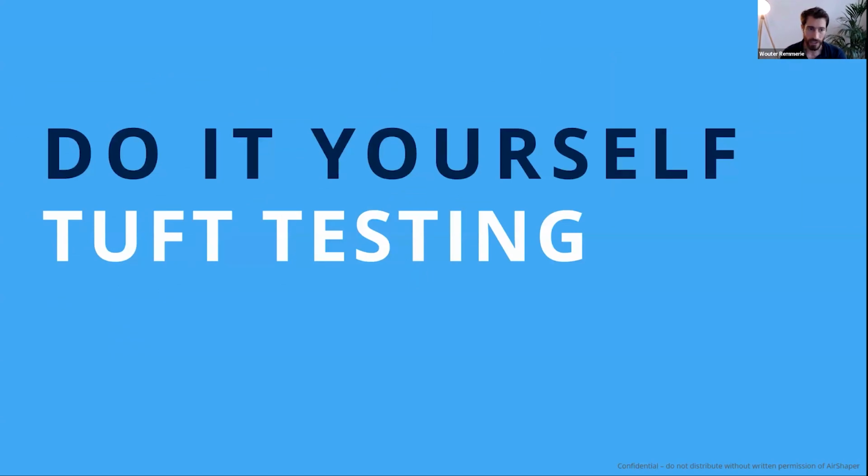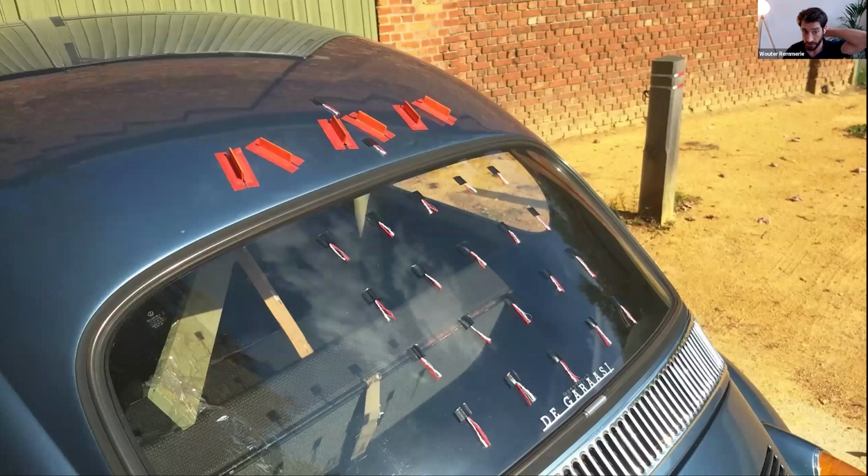And before I jump into CFD, what I find really important is that, as Sandeep mentioned as well, if you're going to follow a track to become an aero engineer, I do think it's very useful to just get out of the books and the classroom and test things yourself. So, for example, you can find this video on our YouTube channel. We went out there, put some tufts, which are these small woolen strands on the car here. We just went driving with a small camera, just my cell phone. We filmed this and we saw how much movement we had, which is an indication of whether your flow is attached or detached and so on.